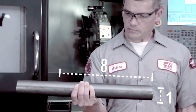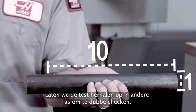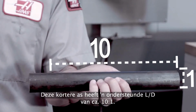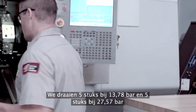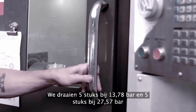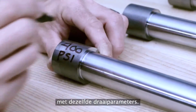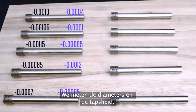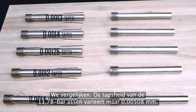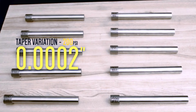But let's repeat this test on a different shaft to see if this trend holds up. This shorter shaft has a supported L/D of about 10:1. Again, we cut 5 pieces at 200 psi and 5 other pieces at 400 psi using identical cutting parameters. We check diameters and find our taper values. Comparing the taper values, we find the 200 psi shafts vary by only 2/10.